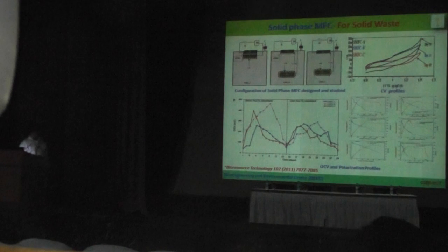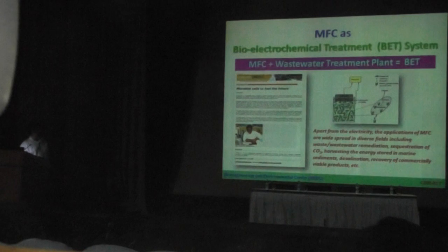We have operated this with domestic sewage for almost one year, and are trying to patent the pilot plant. Specifically, we have designed MFC for solid waste. All the MFCs I described earlier were for wastewater. This one is for solid waste. We tried to optimize the electrode assembly, which is showing good results.